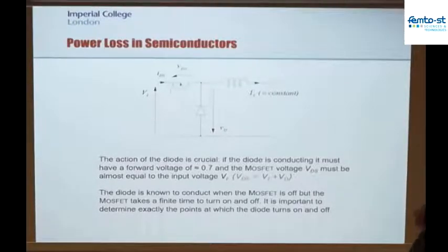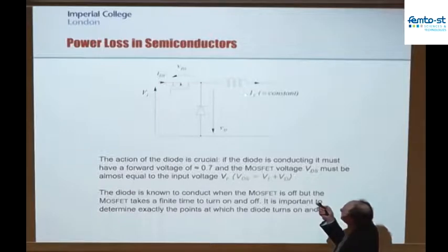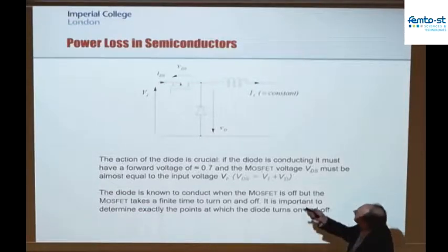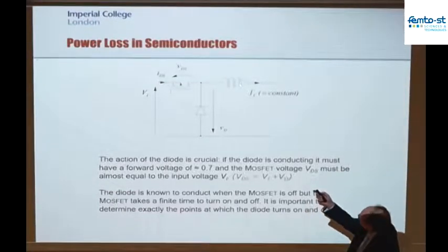Well, if we think about it here, that inductor current during the time of switching between one state and the other is effectively going to remain constant. Current in an inductor does not change very quickly, and we're talking here about being able to switch from the on state to the off state in maybe 10 to 100 nanoseconds. Depends on the size of the devices, depends on the power rating of the system, but we would expect to be doing that probably in tens to hundreds of nanoseconds. So over that period, we'll assume that this inductor current is constant.